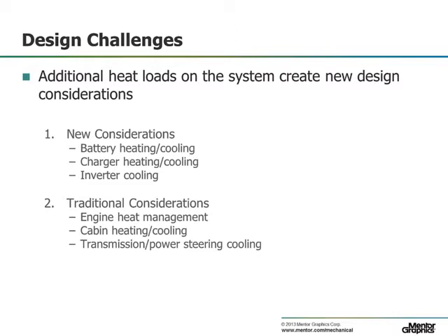Of course, when a system is altered to accommodate these new thermal loads, the engineer must also be sure that the traditional components maintain their operating temperatures, flows, and pressure drops. This may require new sizing to achieve optimal performance and best utilize physical space available under the hood.